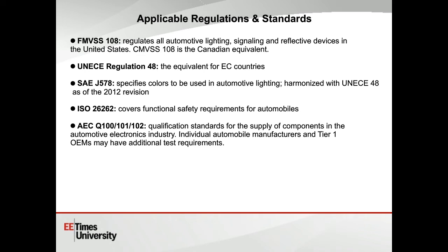This particular standard covers LED-specific issues, such as the light degradation over the rated lifetime, as well as the minimum red LED color content, so that, for example, we can look at a red sign, like a red stop sign, and see it effectively. Because as you know, the red is reflection, and if the LED had no red content, then we wouldn't be able to see the red stop sign very effectively.